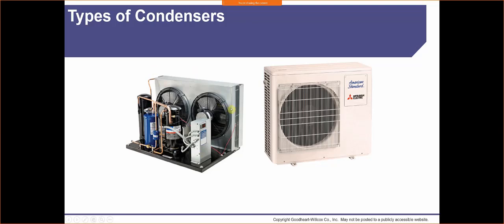So this is the type of system setup that we have. We've got our evaporator over here. I'm sorry, this would actually be our condenser. So we have our condenser, we've got our fans over here, and then we've got a scroll compressor sitting right there. We have just the controls for it all. It's going to tell the system when to turn on, when to turn off, and so forth. Hard to see here, but we've got a filter dryer. We'll cover that in a second.